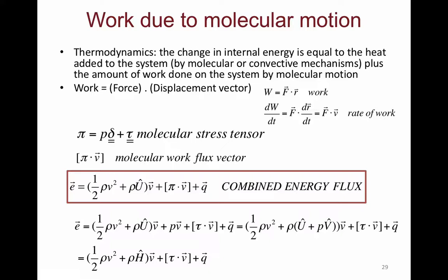And it is Q equal to H, temperature in the solid minus temperature in the fluid. So if I have something like this, this is my solid, fluid, and I have certain heat transfer. Essentially, because of the order of magnitude differences in thermal conductivity, I can support a temperature difference across a solid fluid interface. That's a completely realistic situation.